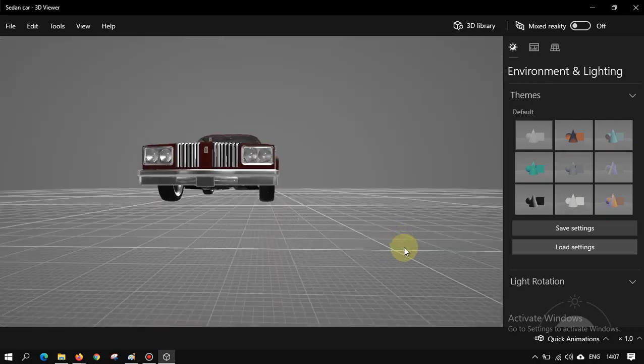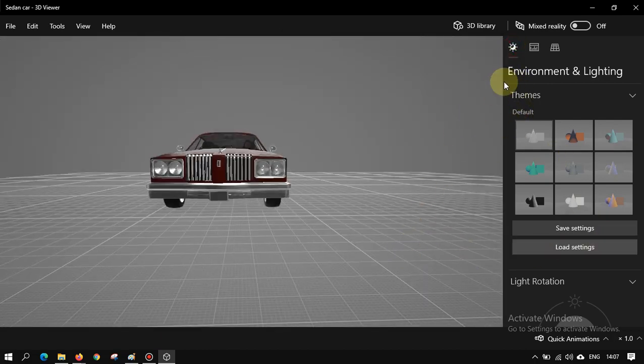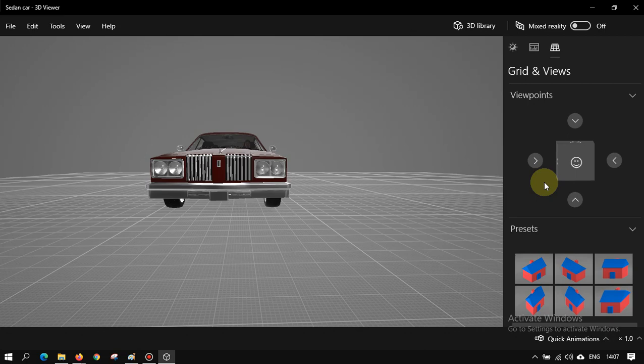So this is what I mean, that you have to consider this type of thing when you are observing an object in 3D. Now you may say, sir, will we be working in 3D? Yes, you will be working in 3D, but not now. But the concept starts from here, that there are 3 views. First view is a top view, second view is a front view, and third view is your side view. That could be right, or it could be left. Fine.